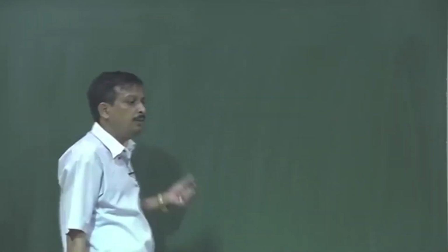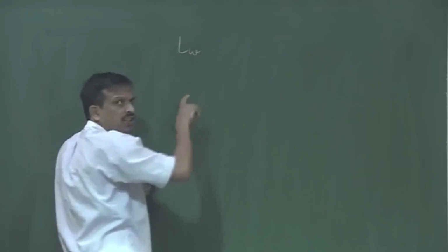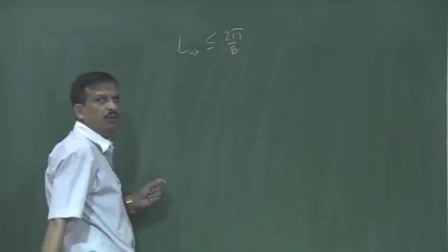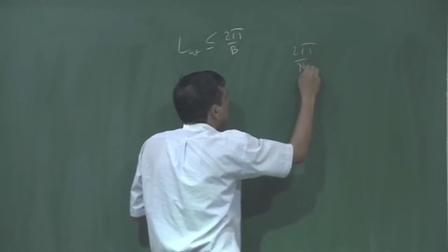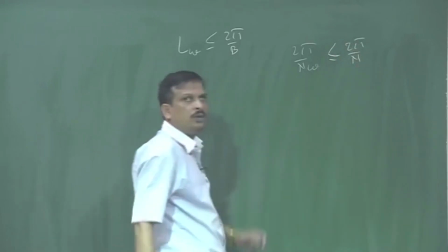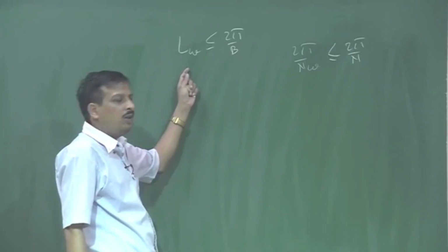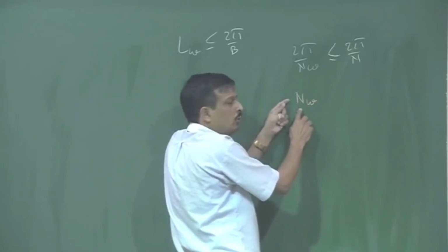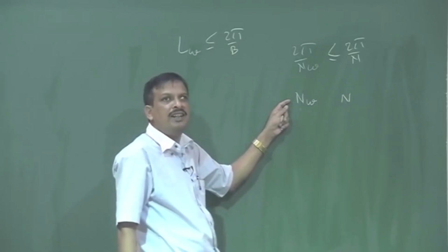Okay. So, from the last lecture, if you use the time frequency sampling, that constant LW, the dissemination in time, should be less than or equal to 2 pi by the bandwidth of the analysis window, and we said that 2 pi by NW must be less than or equal to 2 pi by N. So complete recovery of the signal is possible if I choose the window whose length NW is less than the number of DFT points N I have taken, which defines the number of channels.